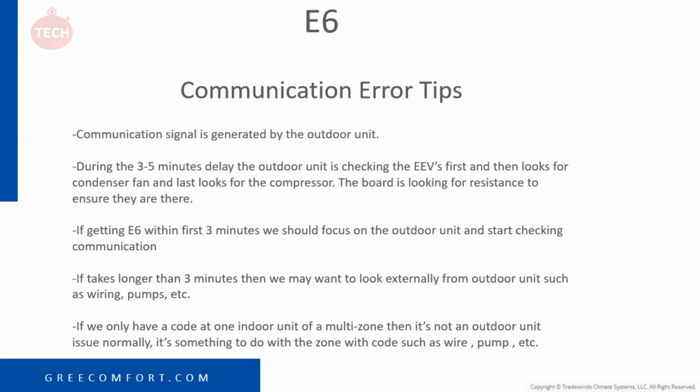If getting an E6 within the first 3 minutes, we should focus on the outdoor unit and start checking communication, which we'll get into showing you how to do that here shortly. If it takes longer than 3 minutes, then we may want to look externally from the outdoors, such as wiring, pumps, etc., which we'll get into all that.